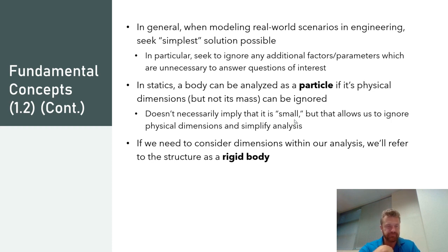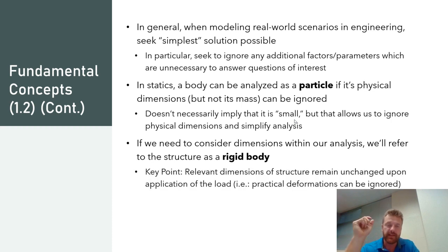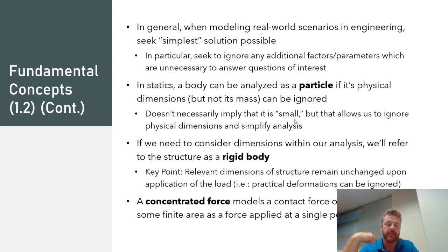So rigid body, we're just going to use that for any body that, when it's subjected to loads, doesn't deform at all, doesn't change its shape, or if it changes its shape, it's ever so slightly and it doesn't actually affect the analysis. And that's what it means by practical deformations can be ignored there in your text.